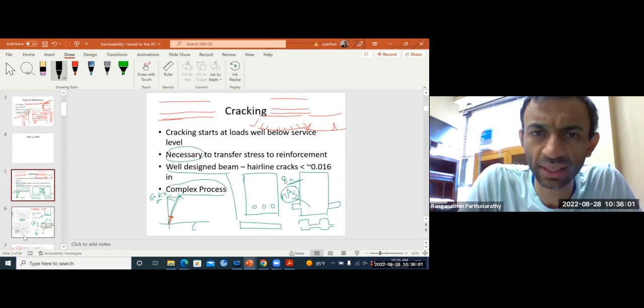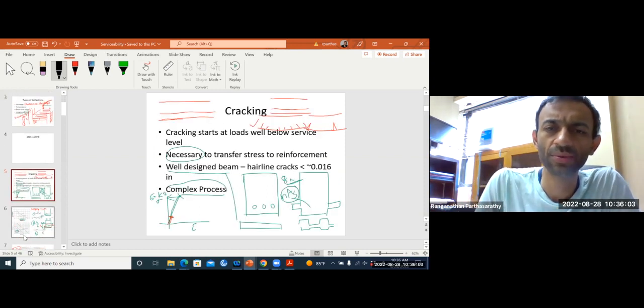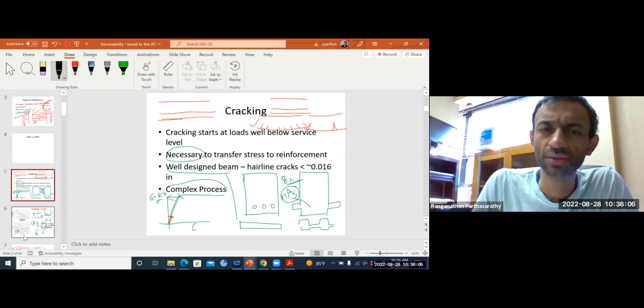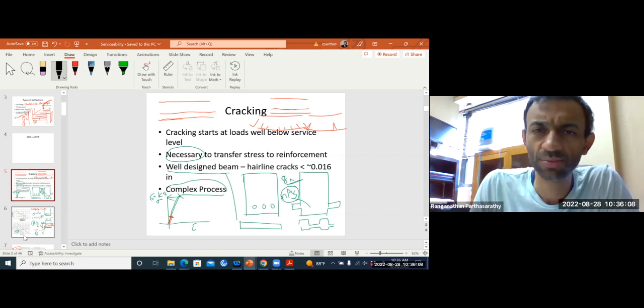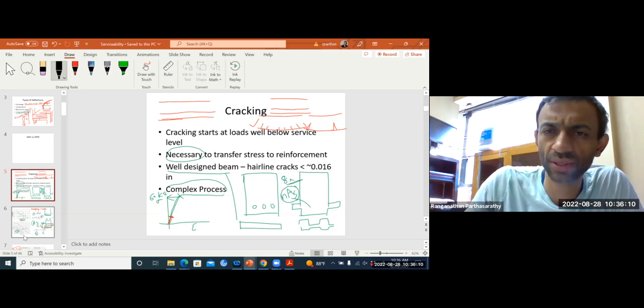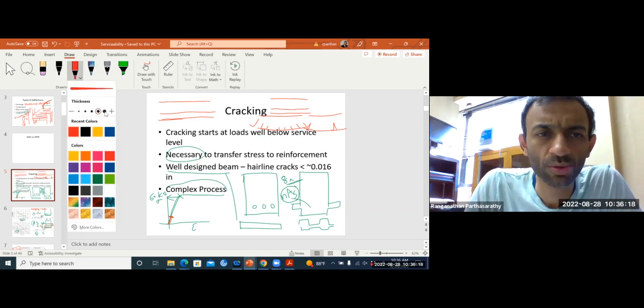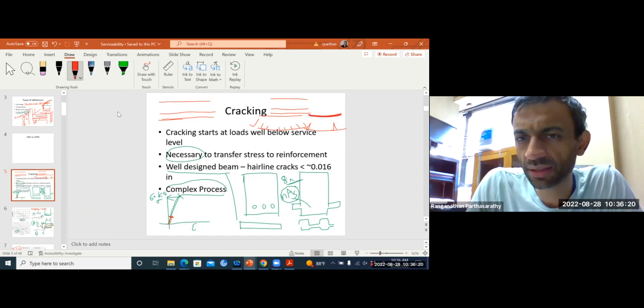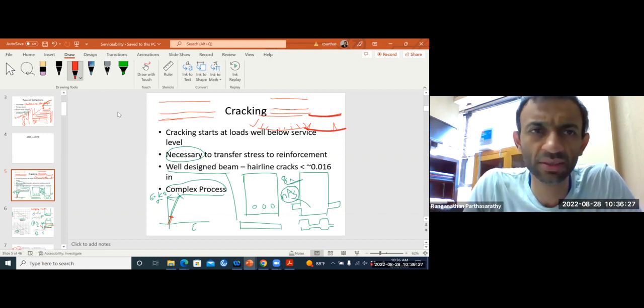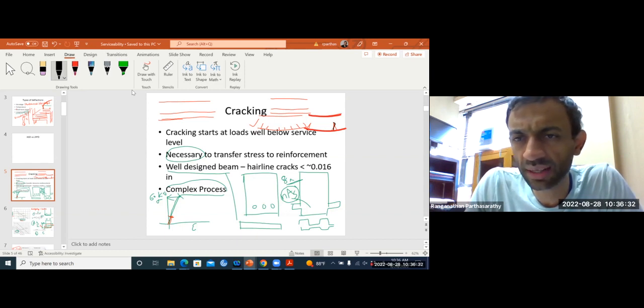I've briefly explained this already. So this is the pattern, the crack pattern for this beam. You can see that this beam had very few rebars, but larger cross-section rebars. So this beam will have wide cracks, but not many.